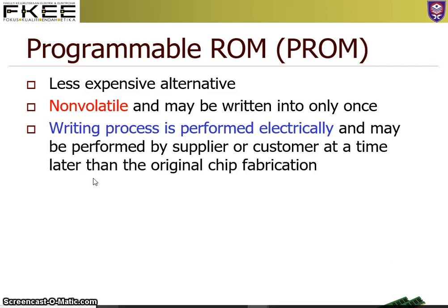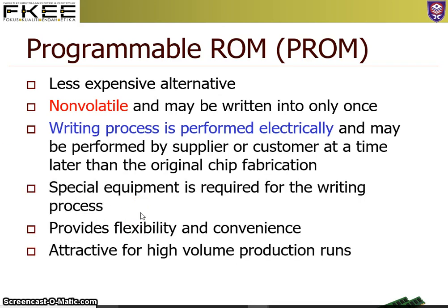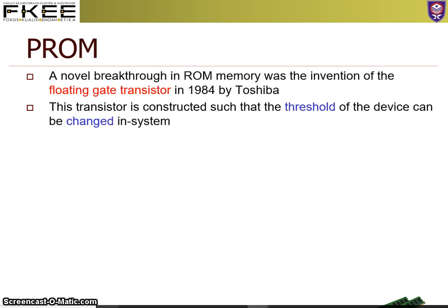Unlike the regular ROM, where you must put the data during the fabrication, for the programmable ROM, after the fabrication you can write what to be input or to store inside it, but you can write only once. You need special equipment to write the data inside this, and it is very flexible and very convenient.